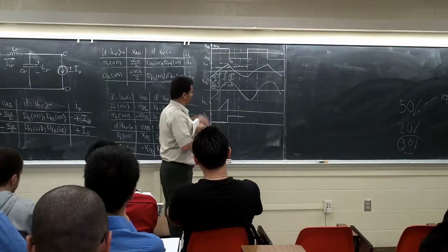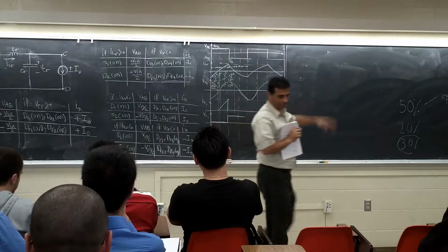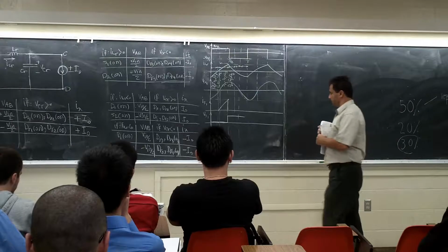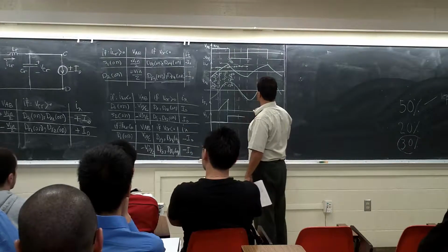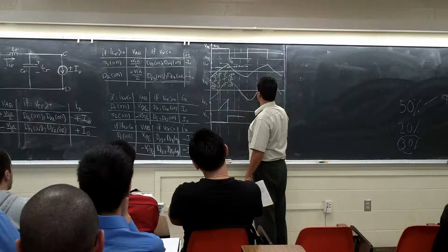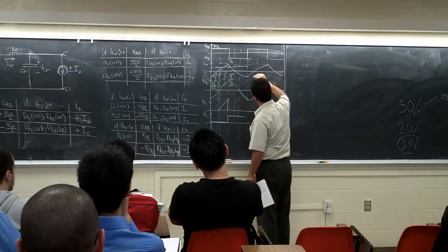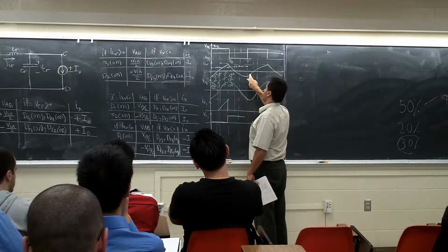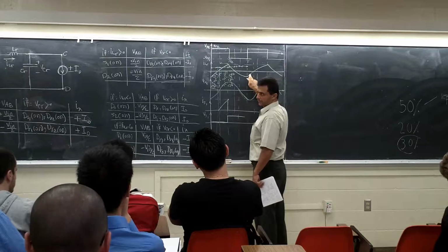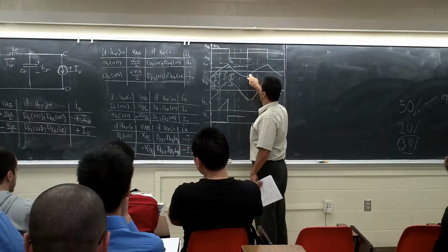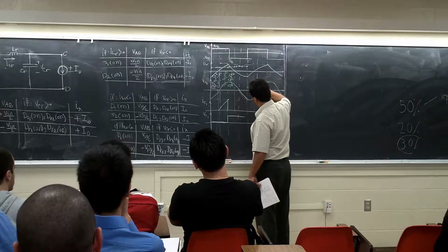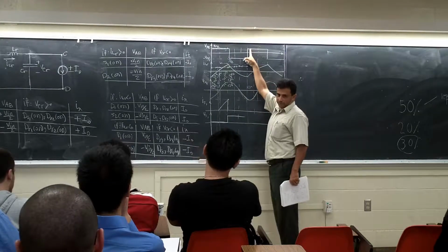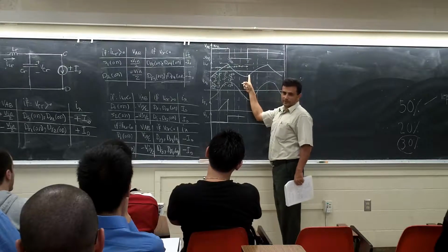Until, we need to go through this sequence to see again when D1 is going to start. Basically, we know when the D1 is going to start. D1 is going to be on here, right? Or here. The current is negative. Yes, the current is negative here. If you look at here, D1 is on. Voltage is positive. The current is negative.